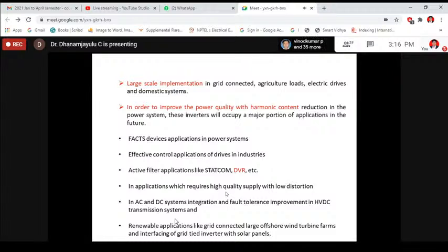This is one of the future scopes. If you reduce the THD, you can connect the proposed inverter directly to the grid, and you can interface it with the DVR. That is also one of the issues, because we need an inverter to inject the voltage. So this is a major issue. As of now, I have concentrated on employing a reduced number of components with fewer DC sources, while generating a higher number of output voltage levels.